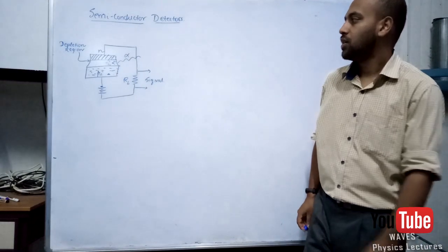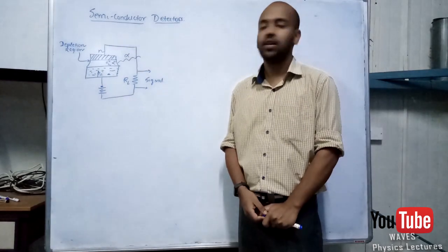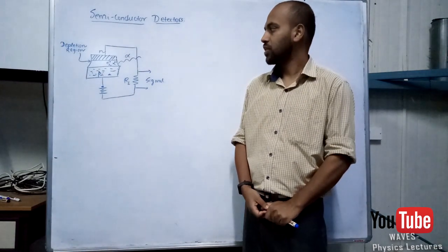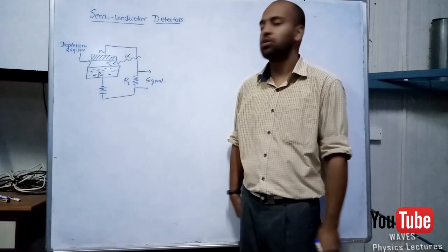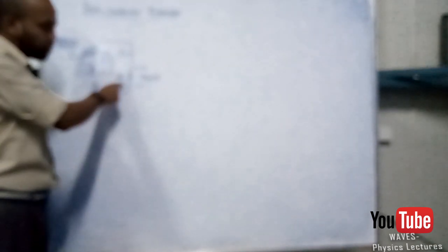As we know, the more the energy, the more electrons and holes we are going to form there. Since we already know about the depletion region, if we want to write down how to produce it in the exam, we can just draw this figure and explain some basic things. I'm not going to write these down because you can explain them in your own words if the question comes. We have an N-type and a P-type semiconductor connected in reverse bias. When you draw the circuit diagram, don't make the mistake: P-type is connected to negative and N-type is connected to positive, across the load RL.